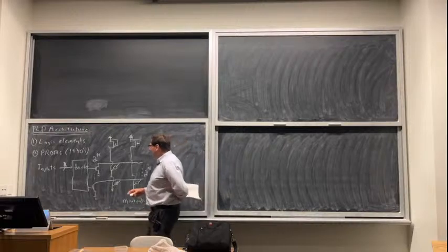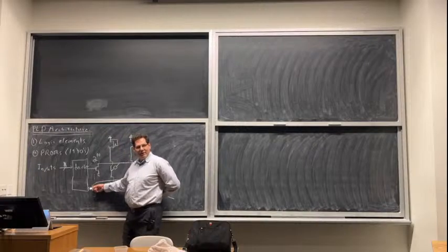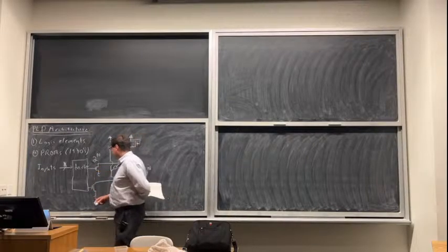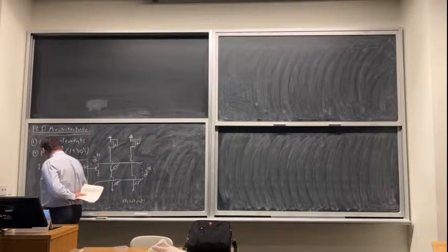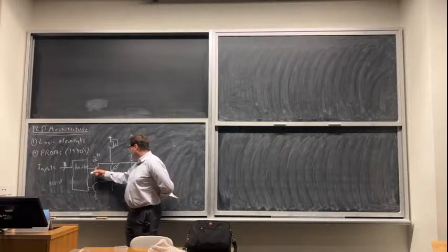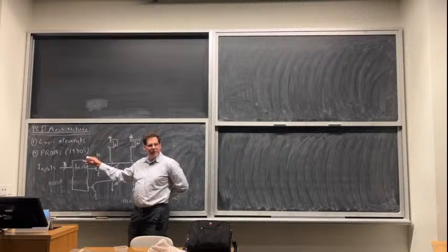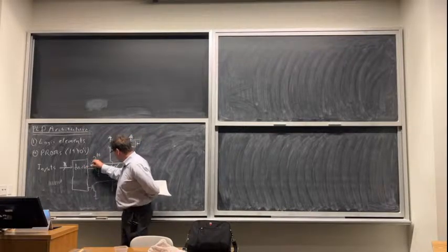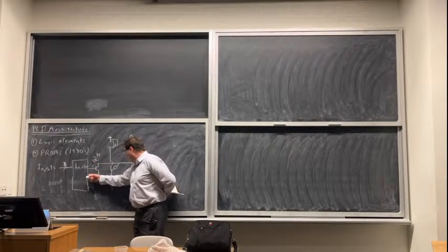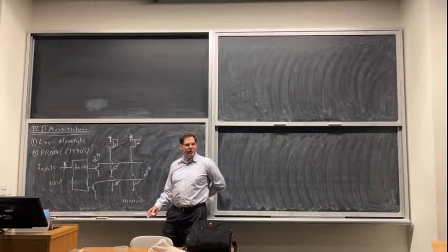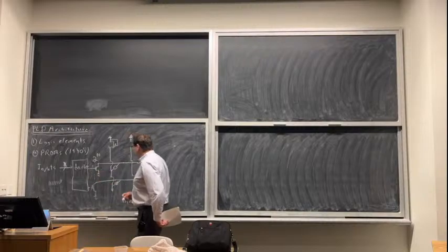So 2 to the n minus 1 of these transistors are not going to be on, and 1 will be. Let's say we put in the pattern all ones. Maybe we've got 8 inputs, and we put in 8 ones. Then our highest order output is going to go high, right? So we've got 255 outputs from this decoder. This is the only one that's going to be logic 1. All the other ones are going to be logic 0. So this transistor is going to be on. All of the other 255 rows, their pull-down transistor is going to be off. So this is the line we care about because it is trying to go to ground.